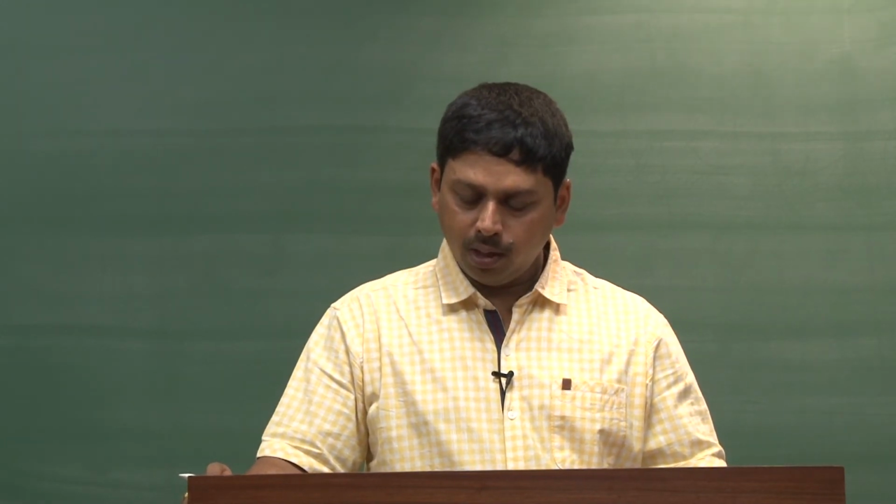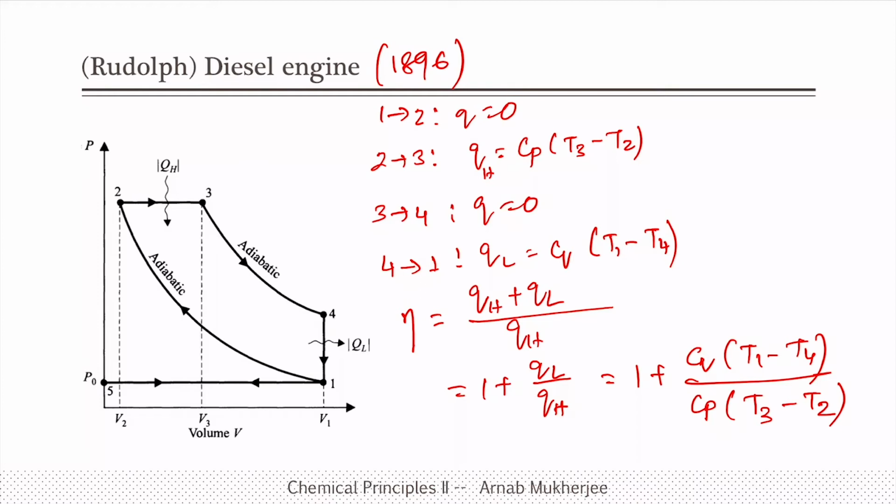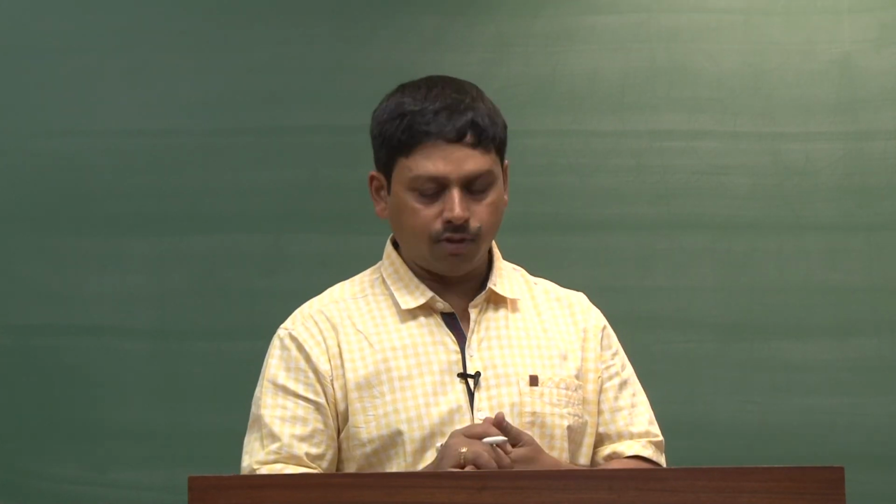Okay, so one important thing to discuss here is that in both the gasoline engine and diesel engine, there are constant pressure and constant volume processes. In gasoline engine there are two constant volume processes, and in diesel engine one constant pressure and one constant volume process. Now, in constant pressure or volume processes, the temperature changes all the time, and therefore, in order to make a reversible engine you need to place this system in an infinite number of heat reservoirs. Therefore, it is difficult to compare with a Carnot engine, which works between a fixed 2 temperature reservoirs.